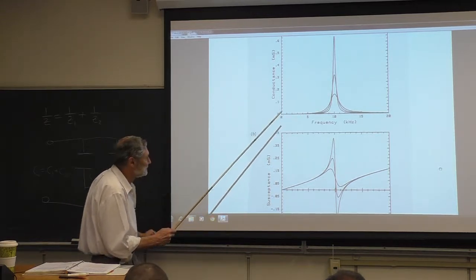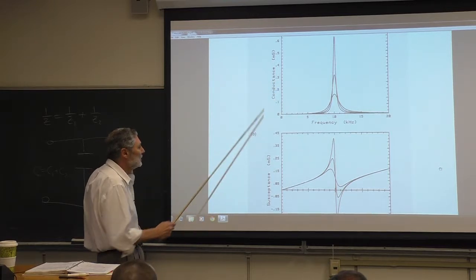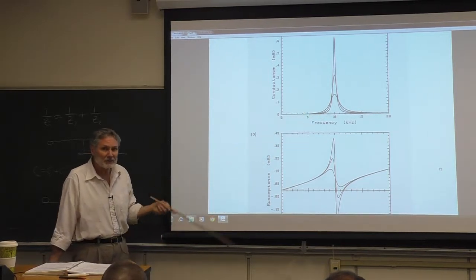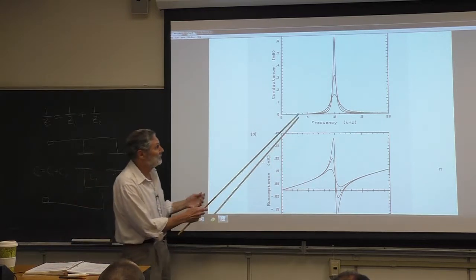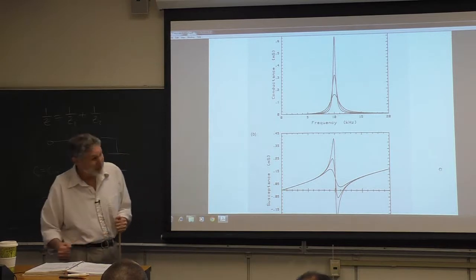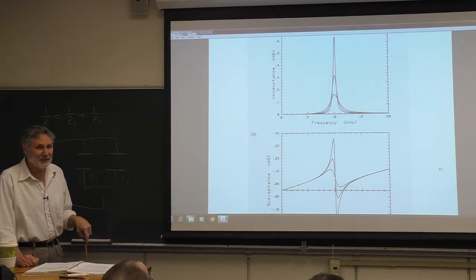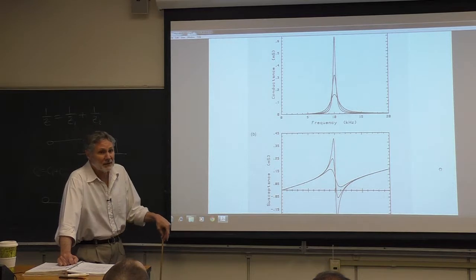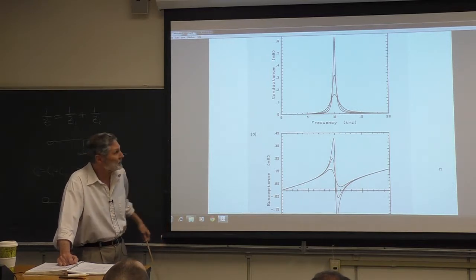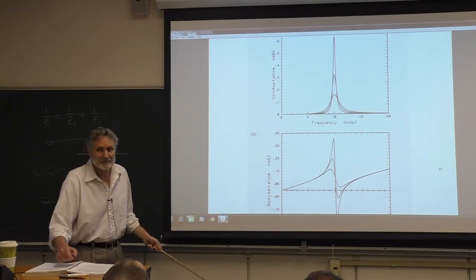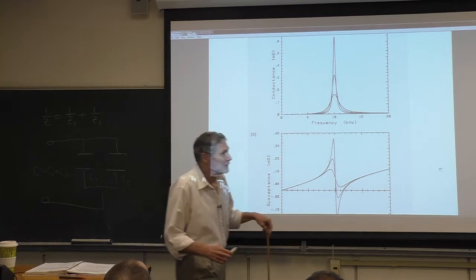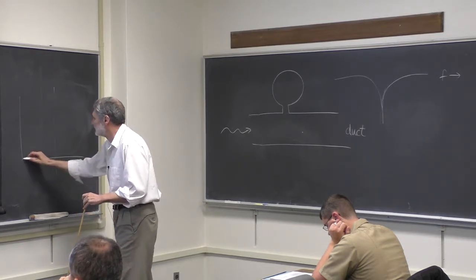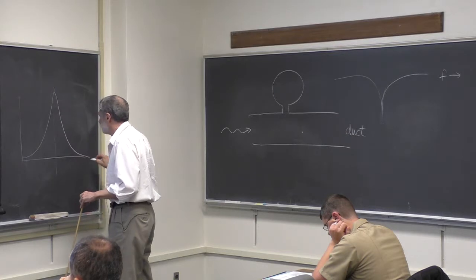So here's the conductance, the real part, and the susceptance, the imaginary part of the admittance, as a function of frequency. The first thing we notice is that this looks pretty close to a normal resonance peak for just a mechanical oscillator. But there is a difference there. Does anybody see it? If you just take a driven damped simple harmonic oscillator and look at the amplitude of the response, it doesn't quite look like this. This is amplitude, not power. They don't spread like that. The typical case, you have this resonant frequency here, a curve that goes like that, when you look at different quality factors.